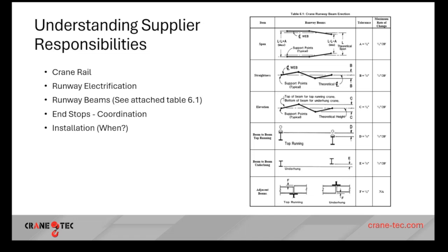We got one other question here from Joe Allen. How do manufacturers typically rectify or allow adjustment for the 1/4 inch or 3/8 inch tolerance required for crane beam span and straightness, versus a tall pre-engineered metal building with an L over 500 tolerance, which could be closer to 2 inch?